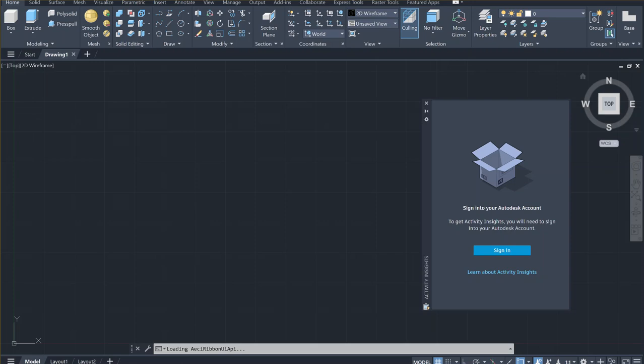This is going to be a smaller model version of the vertical wind blade, and we're going to initially create one single blade, and then we're going to make 3 copies around the circle. Because it's so small, the height is going to be only 6 inches. So I'm suggesting you start your AutoCAD. As soon as you start AutoCAD, there are a number of things you should be doing. For example, units are important. Set your units to engineering units.